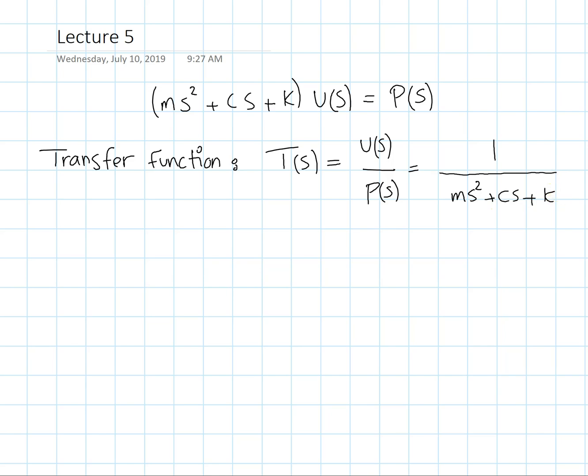And a transfer system really is basically a transformation between the input and the output. So for some input p(t), this is my transfer system TS, and my transfer system is my equation of motion, or 1 degree of freedom system, with the c and the k and the mass. My output will be U(s). Or I could express it in time domain, it doesn't really matter, u(t).